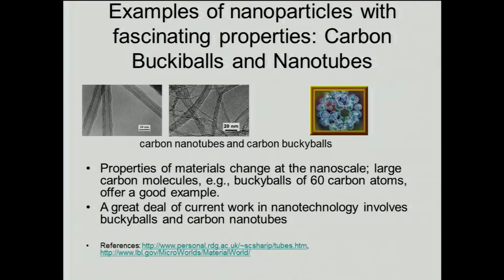The other part which makes nanotubes very important, even for biological purposes, is the surface properties, as we said, that it dominates. Surface property dominates means if you change the surface slightly, its conductivity changes. So, if you expose the nanotube to oxygen, oxygen gets on the surface of it and its electrical property changes.